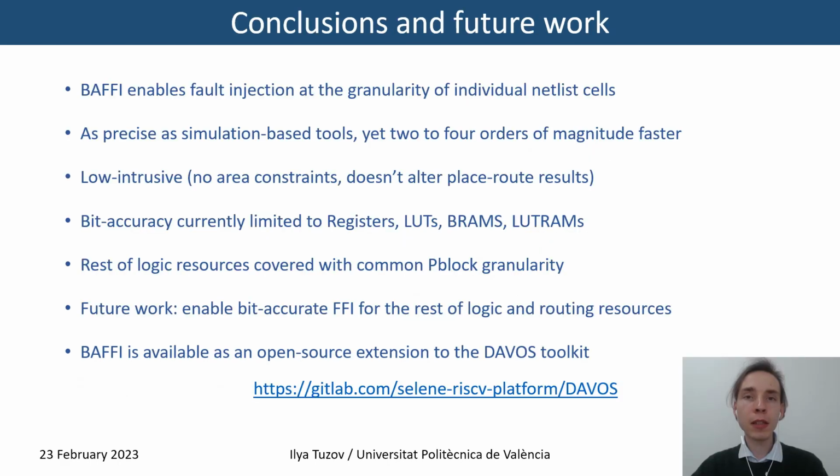So, in conclusion, the bit-accurate mapping of essential bits allows BAFFI to perform very fine-grained fault injection experiments. And this is something that previously was only possible with simulation-based fault injection. But now it can also be done in FPGA, and 2 to 4 orders of magnitude faster than in simulation. And this makes BAFFI very useful for verification of complex designs, like multi-core CPUs and systems on a chip.